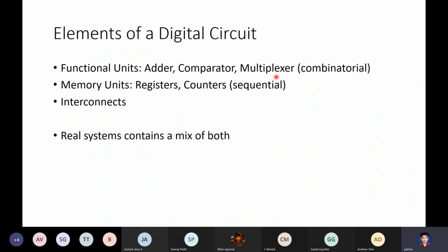So usually, the data path is not a fixed circuit element with a fixed function. It's a collection of circuit elements, and the control path determines in which sequence these elements will activate and compute something. Depending on the sequence in which they are activated, you realize different operations, different functions. Okay, so that's the abstraction, a data path and a control path.